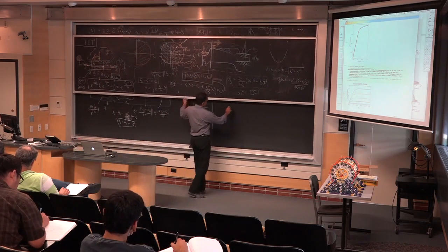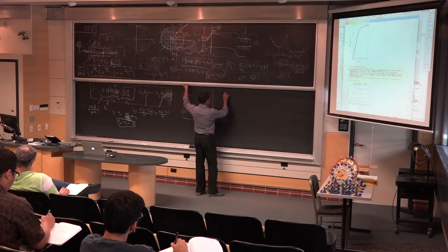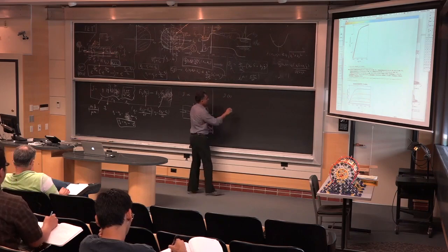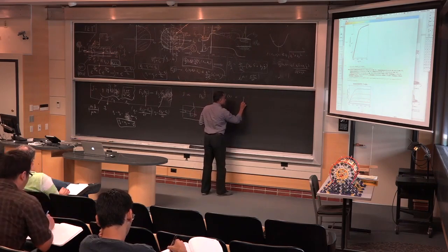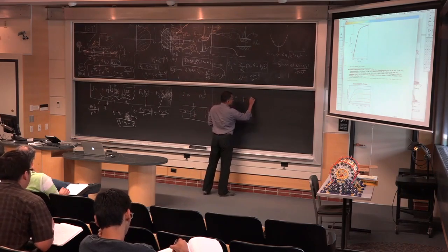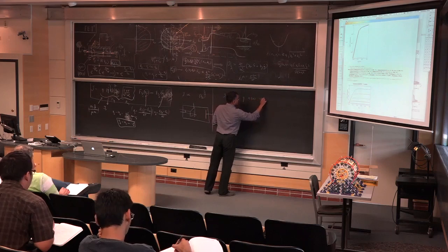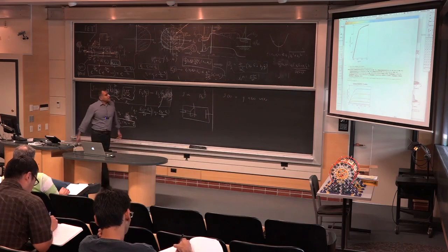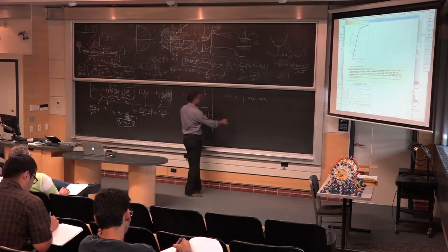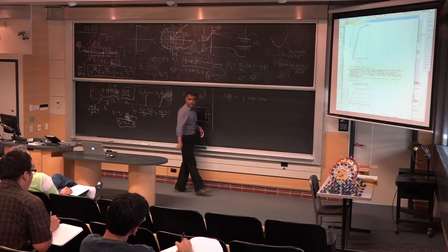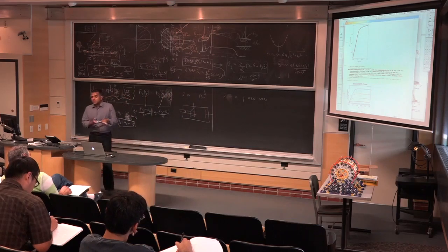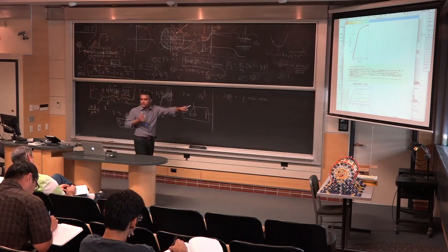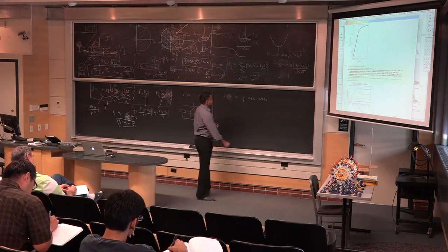So he says that, look, the current at any point in the transistor, J as a function of x, current density per unit width as a function of x, is equal to electron charge, if you're moving electrons, times the electron density times the electron velocity. That's straightforward. Not much to say about that. And this is also true quantum mechanically, but the beauty of it is it really doesn't depend on x. The current is continuous. If a certain current is flowing here, it's also flowing there. This is a very important relation now.